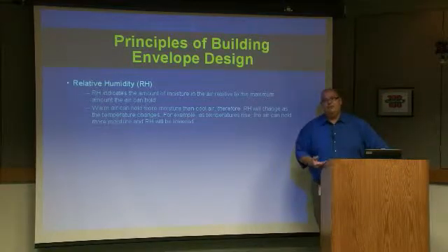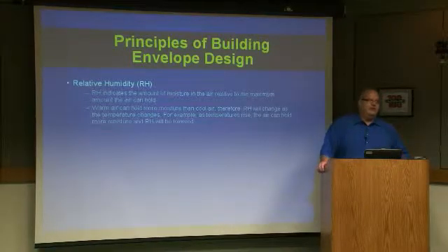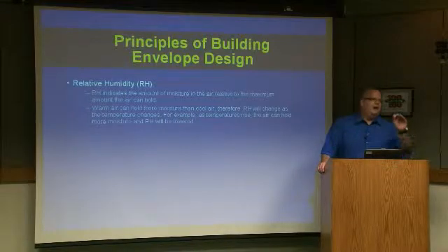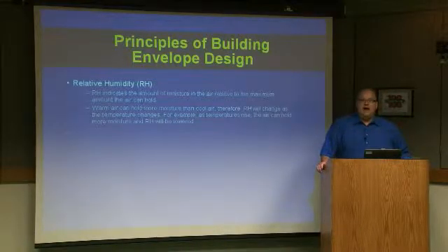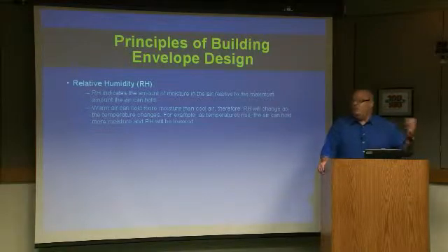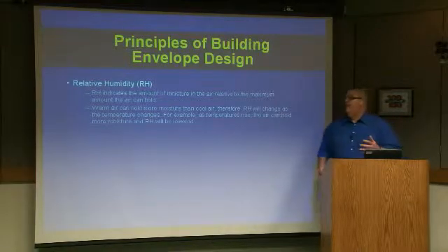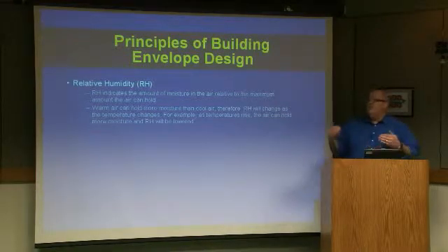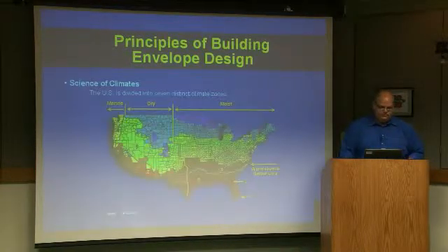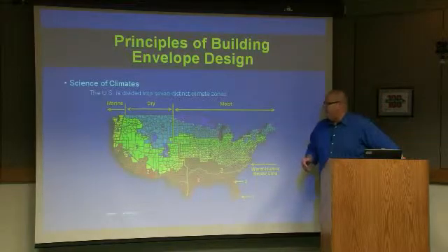That's that ASHRAE Standard 160 you've heard me talk about before, design criteria for moisture control in buildings. This is the new yardstick. We used to do dew point calculations where we'd figure out if condensation would occur. We already know that if condensation occurs for 1 day, it's way too late. We're already in mold growth potential. Now what we try to avoid is 80% relative humidity for 30 running days when temperatures are above 41, below 104. And that's our guideline for how we're going to deal with humidity. Now we know what humidity we can live with, less than 80. This becomes really important in terms of moisture drives.